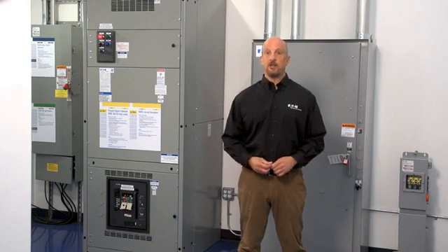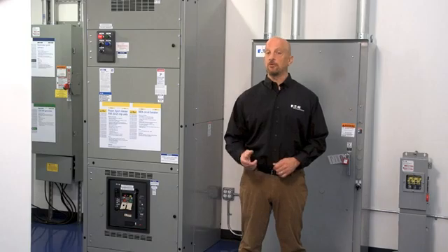The new Power Defense MCCBs add significant protection and monitoring capabilities with their new trip units. Low voltage power circuit breakers have many more components compared to the MCCBs and may be electrically operated, meaning you can turn them on and off remotely. This is possible because of the stored energy in the operating mechanism. As we mentioned before, they can also use a variety of trip units to enhance protection and safety.